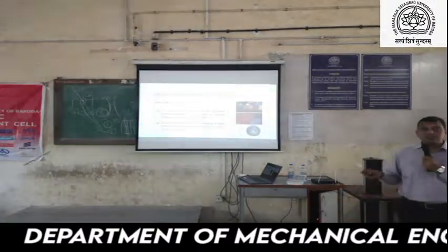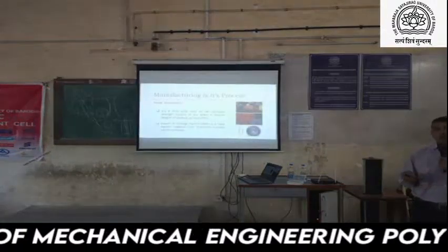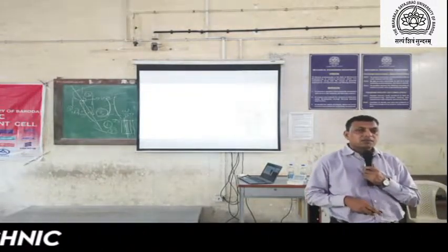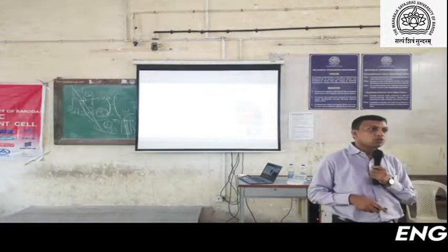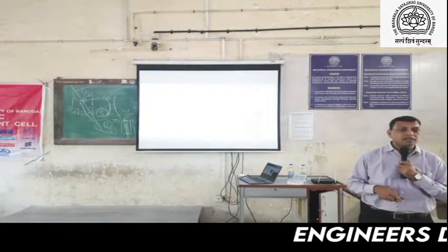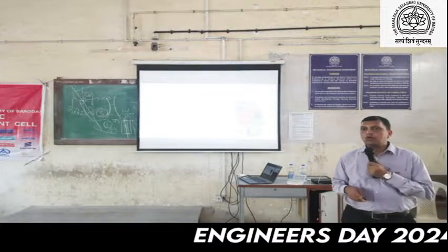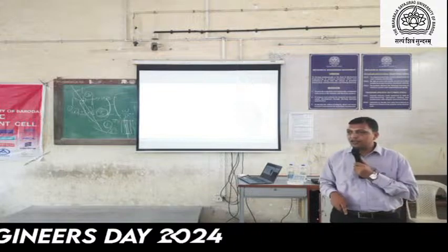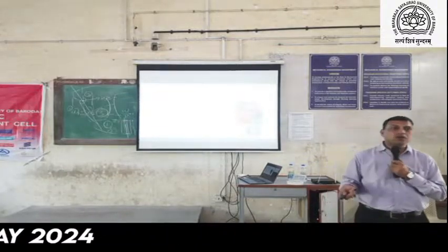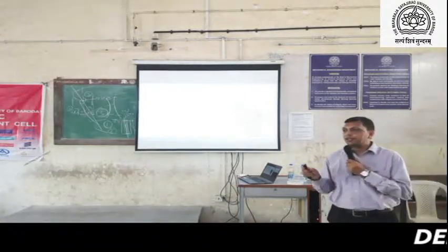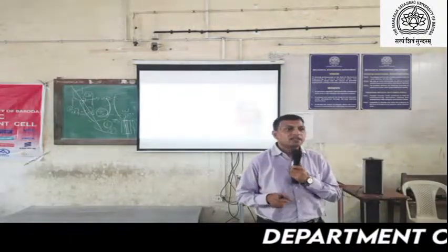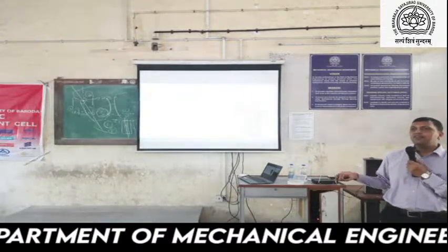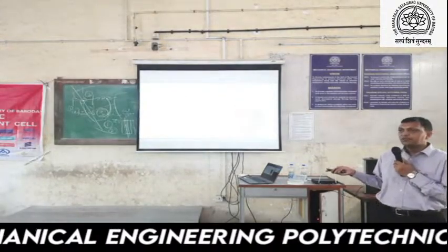So why is heat treatment required? Why do we go for case hardening rather than through hardening? Basically, if we go for through hardening, the material becomes brittle, so failure will be early. If we go for case hardening, the material stays softer in the core, so it gets higher ductility. It can take a higher stress value. So that's why we require heat treatment for case hardening.